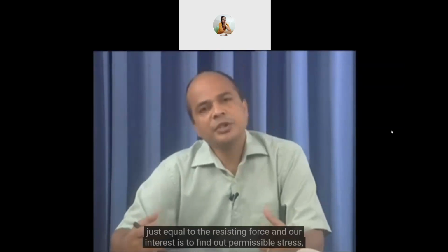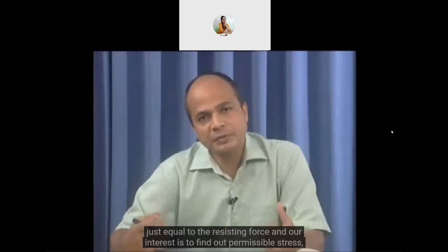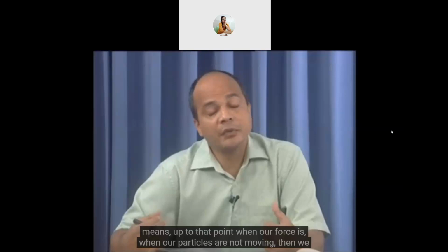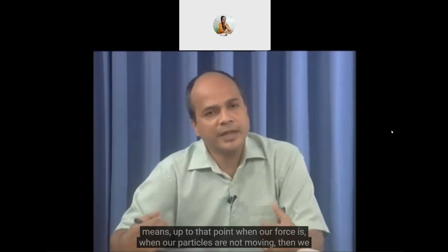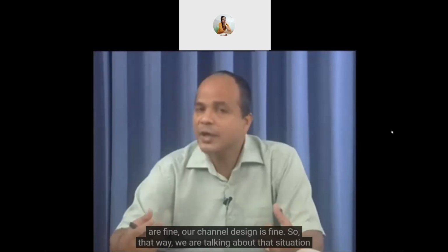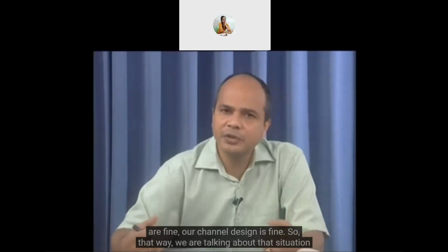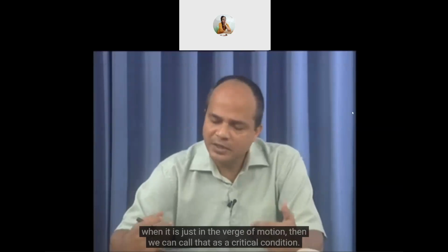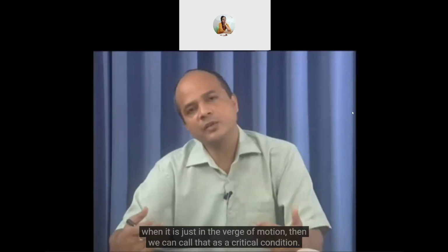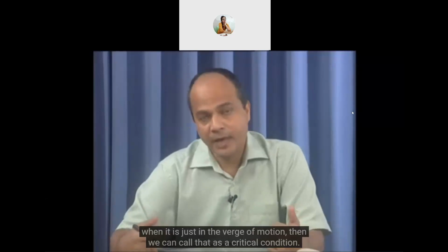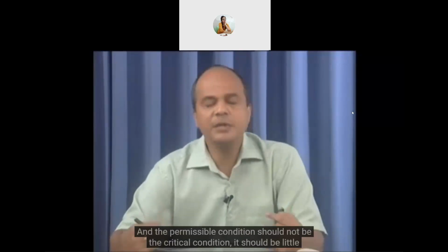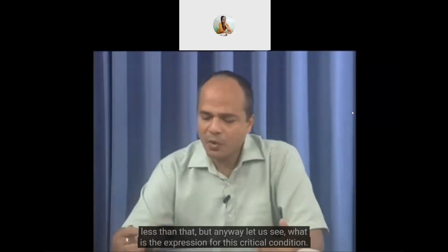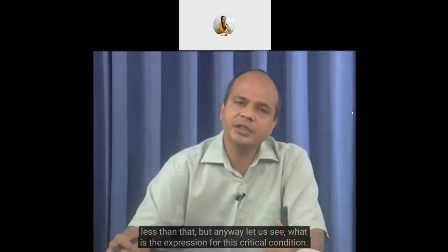And our interest is to find out the permissible stress. Up to that point, when our particles are not moving, we are fine. Our channel design is fine. So we are talking about that situation. Of course, our permissible force may be a little less than this particular force, but when it is just on the verge of motion, then we can call that a critical condition. The permissible condition should not be the critical condition. It should be a little less than that. But anyway, let us see what the expression for this critical condition is.